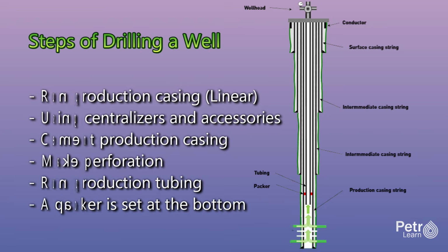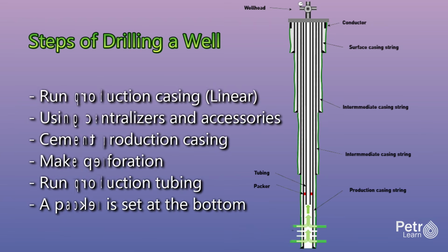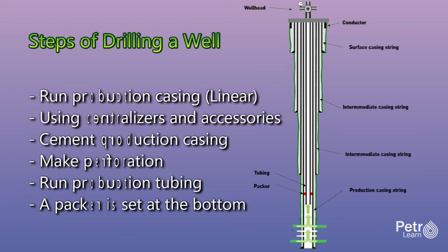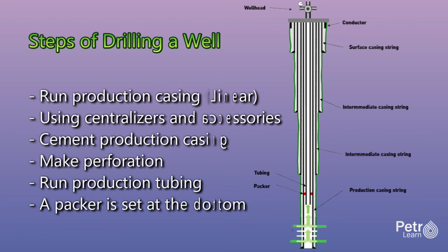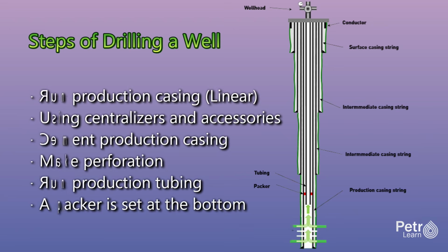The cementing operation for the production interval is critical because the quality of the cement bond affects well performance and zonal isolation. If cement doesn't fulfill the standard requirement of isolation in the annulus or has channels, different zones can communicate behind the casing, and the well may produce water or gas from unintended zones. After cementing and waiting for the cement to cure, the well is prepared for perforation. Perforating is the process of creating flow paths from the reservoir into the wellbore by shooting holes through the casing, cement, and a short distance into the formation.